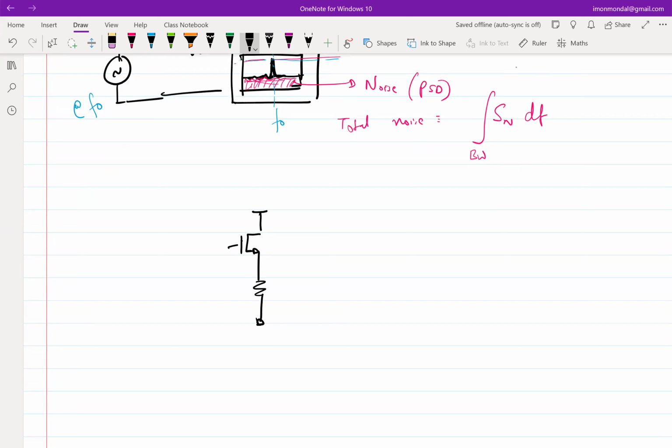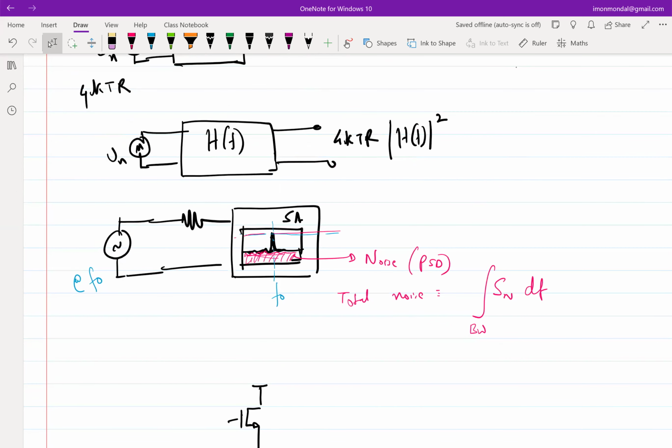Yes. So the spectrum analyzer doesn't have any noise sources of its own. Like it doesn't contribute. Everything will have a noise source, just that a good spectrum analyzer will have a better way of suppressing noise. It will not contribute too much noise on its own compared to a poorer spectrum analyzer. So how do you characterize a good spectrum analyzer or not? You basically check the noise floor, right? Per unit bandwidth, how much noise it gives on its own when nothing is connected. If it already gives more than the signal you are receiving, then there's no use. So that's the difference between a good spectrum analyzer and a not so good one.